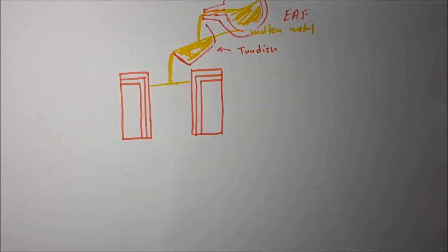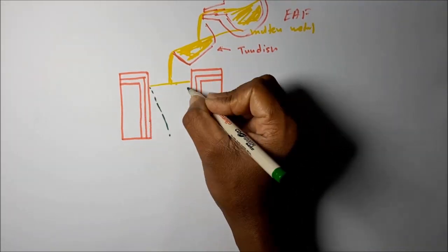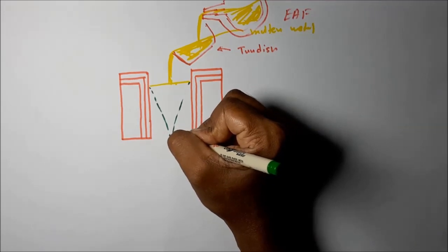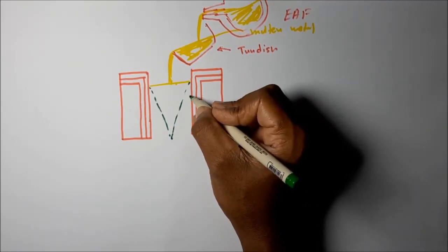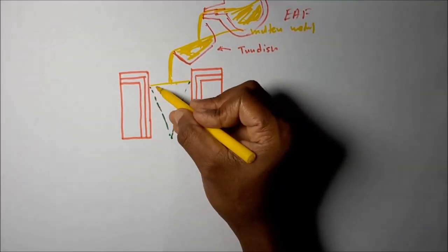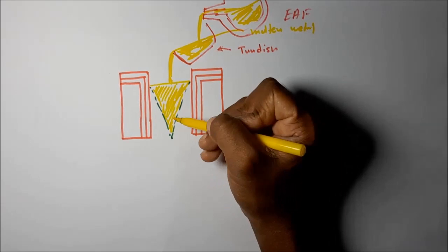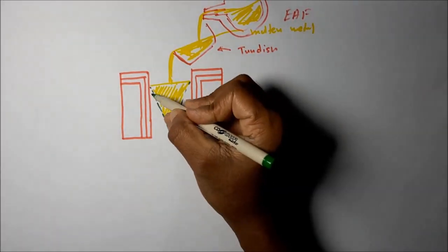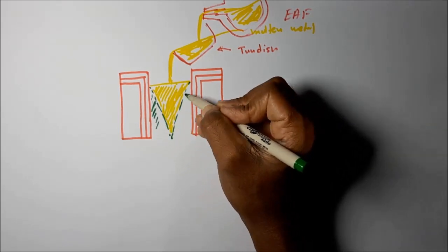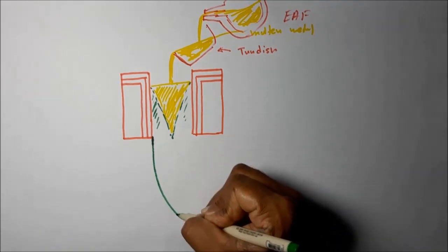This chamber. So while passing through this mold, it gets solidified. Then it forms this kind of solidification pattern. Initially this surface is solidified. This is how it's solidified. Then this is still molten metal. Only the surface closer to the mold wall gets solidified. Only this area gets solidified. So then the solidified part is taken out in this manner.